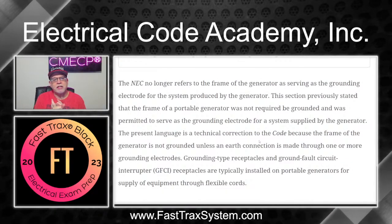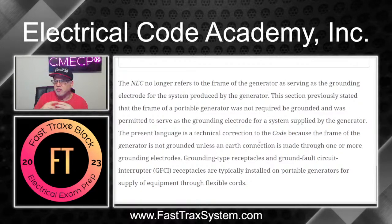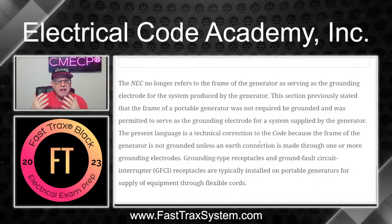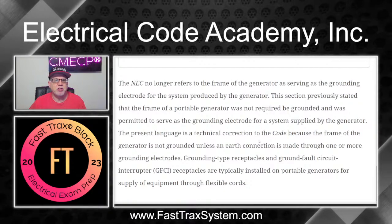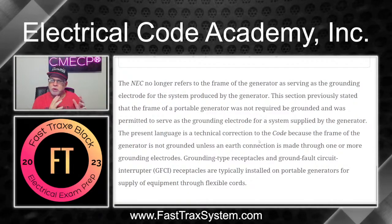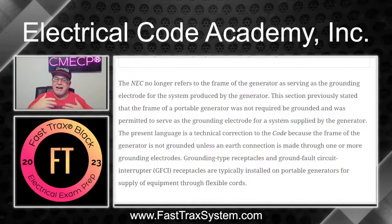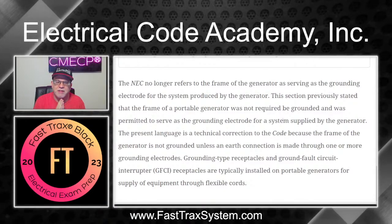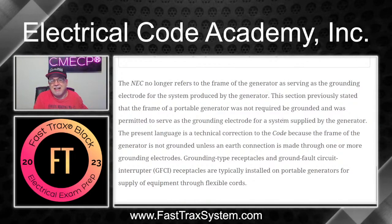Now, remember, we're looking at the 2023 edition of the National Electrical Code. And why is that important? Because there was basically a change in terminologies and in technical jargon and how we explain something. Let me read it to you and you'll get a better understanding, especially if you're in a 2020 or 2017 edition and you see us doing this 2023, you're thinking, okay, isn't that metal frame acting as an electrode and that's why we don't have to have an electrode? No, it's not, because that frame is not connected to Earth, so it is not an electrode, right?